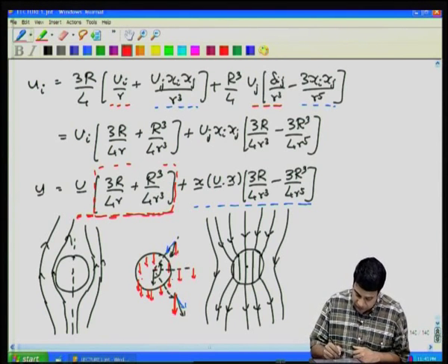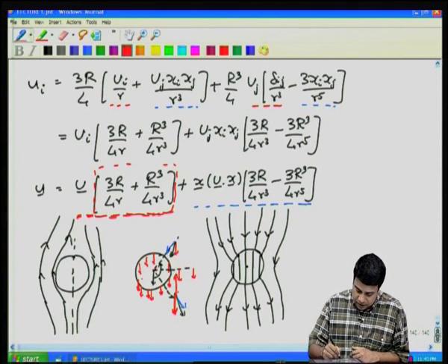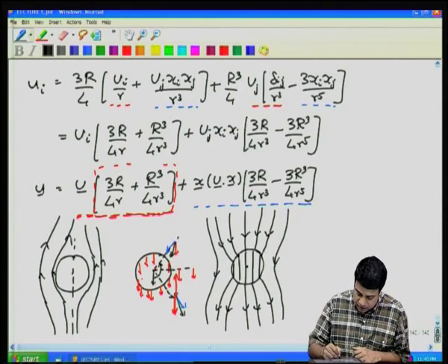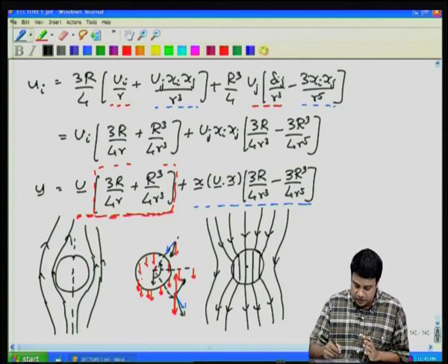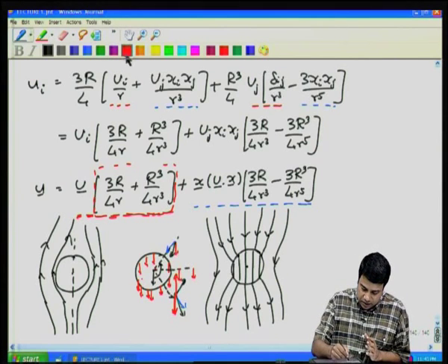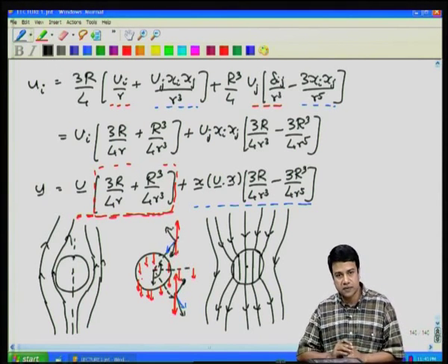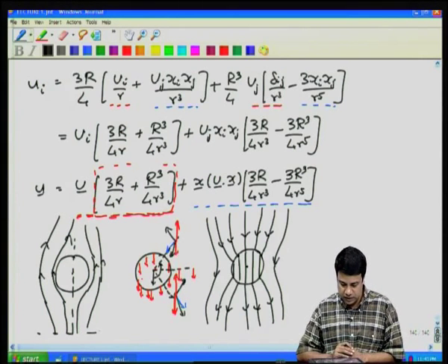Therefore, I have a larger velocity being added over here, and the net resultant that I get due to these three velocities will end up being something in this direction. So, it will be outward at the bottom of the sphere, and similarly if I subtract out this capital R over here, I will get a velocity that is inward behind. And that will give me this profile in a fixed reference frame. So, we have got the velocity profile, we have got the velocity, we have got the pressure.